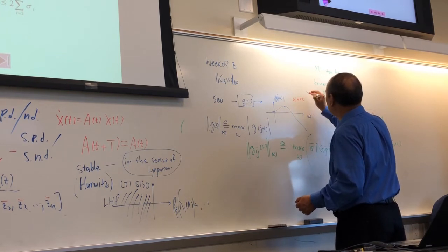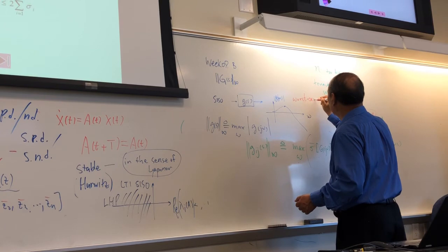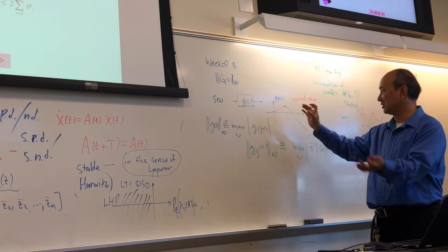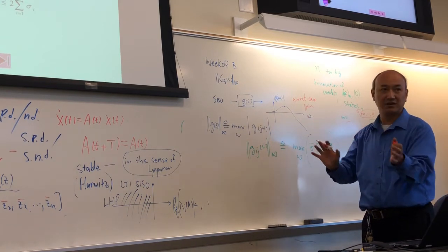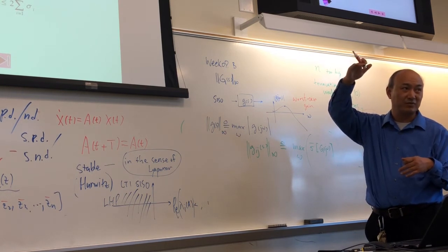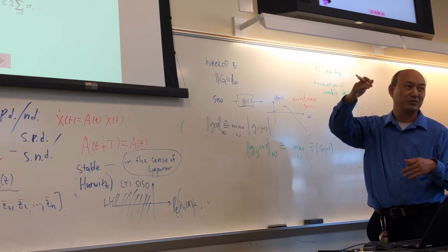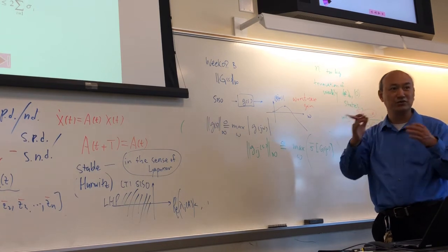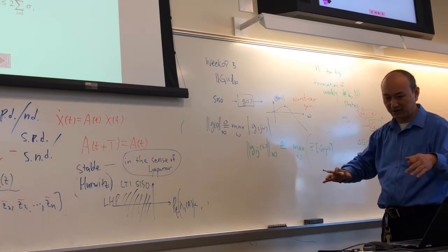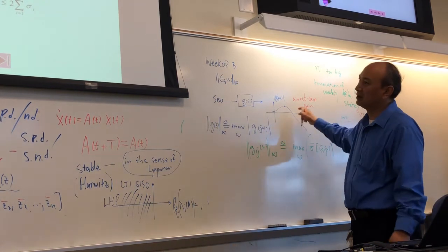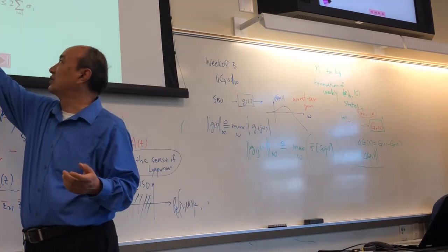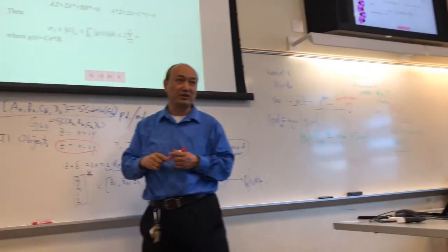Worst case gain. If you have the two norm, then that is just adding all the energy together. You don't know where your peak is. So the infinity norm is basically the worst case norm. The two norm is an energy. So total energy should be less than something. That's performance. So computing the infinity norm of a matrix transfer function is very involved actually.